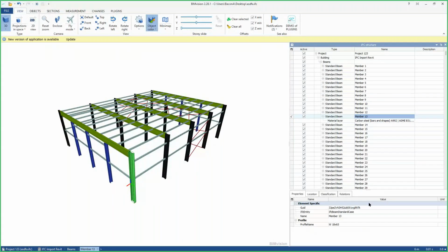The good part about this is that because we saved that info in the IFC, we can use that info again, like I just did with the export. The members, like I said, save the GUID. This is good because it allows all of us to compare IFC files. If we have two IFC files where the GUID of the objects is the same, this will allow us to compare sections and materials, which is good.